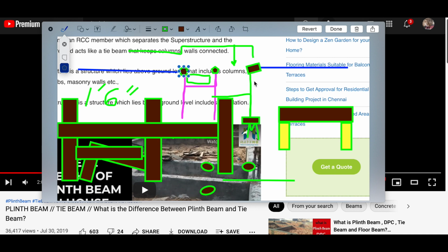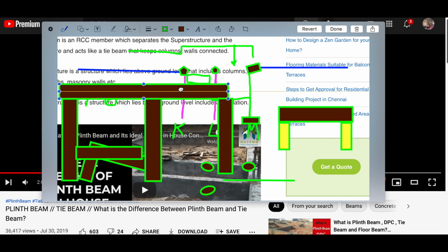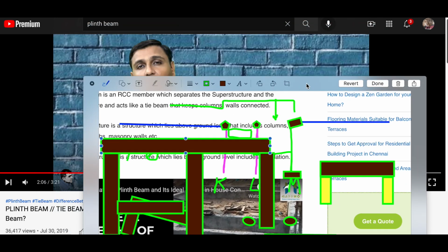As you can see, that's on a little bit of an angle. So if this goes down, it could rotate that column or tear out some reinforcement, which would make this weaker. More so, the slab. Once we get this weaker, the spans of the slab are what matters, and how much this falls down and tears at the supporting column here, right about here on M, that's what matters there, or tearing out, ripping apart. And let's move over here.